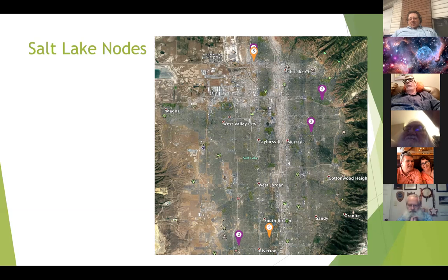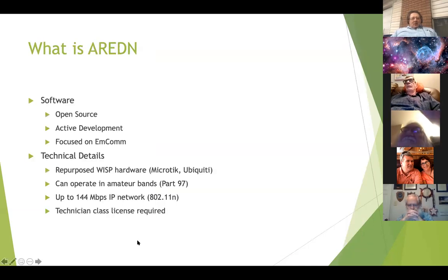Typically, the antennas that you're going to be using, you might get 10-15 miles out of. Inside your house, you might have it set up with a very local setup that only works inside your own property. But yeah, you can get up to 90-mile range out of these things because it's microwave and line of sight. And being on the amateur band, we can actually use higher power than the commercial Wi-Fi stuff would be using.